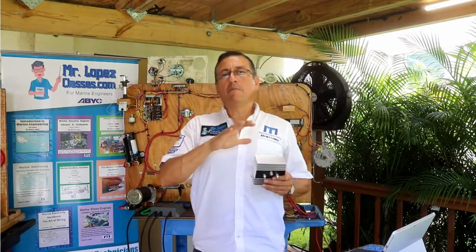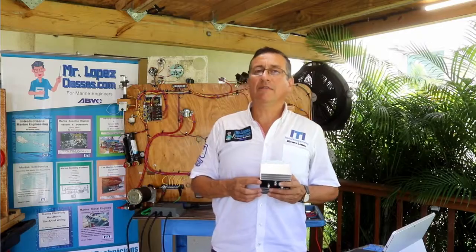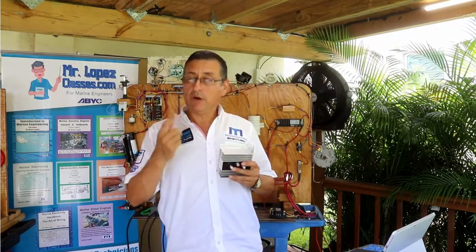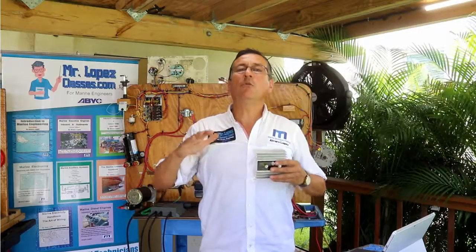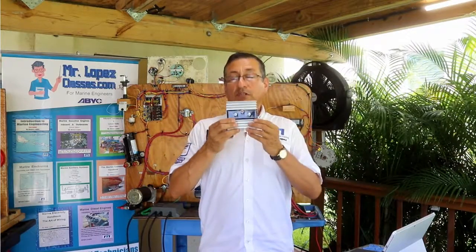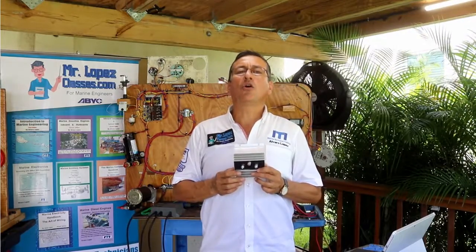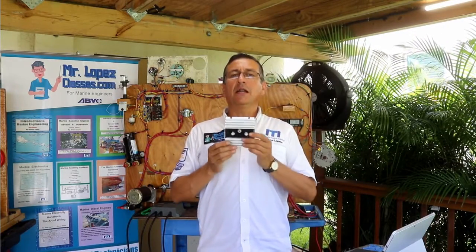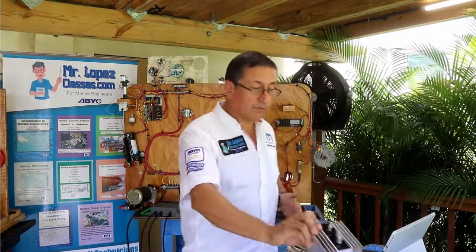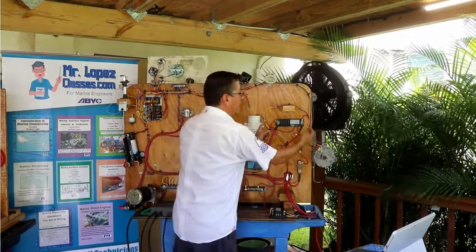The ACR should be mandatory. If you have more than one battery bank, and you have more than one source of power, the recommendation is to use ACRs in order to keep the charge of the different battery banks equally stabilized. For that reason, the name of this equipment is battery stabilizer, or battery regulator, or ACR, automatic charging relay. Okay, this is with one input and two outputs, and this is combined.